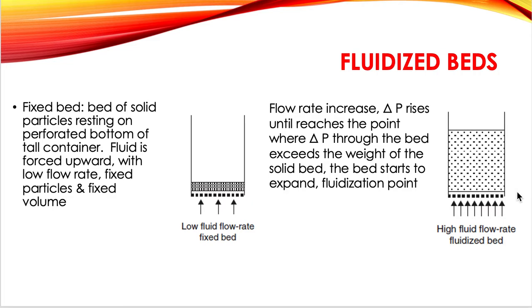In the case of filtration, particles are deposited in a filter medium while the fluid passes through. For absorption or ionic exchange, the fluid moves through a bed of solid particles, and these solid particles usually don't change their characteristics. All of these processes are governed by the same law that we looked into in the previous video, which is Darcy's law. And Darcy's law is actually looking into permeability.